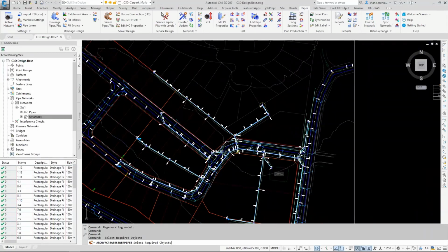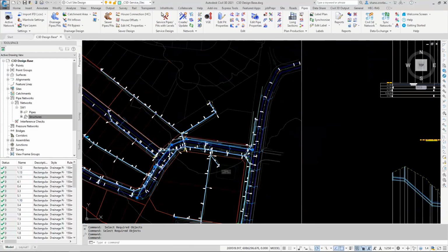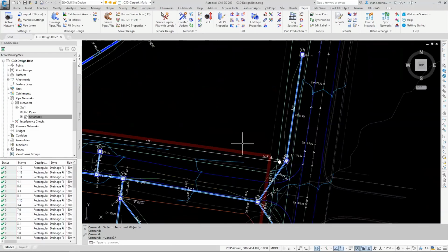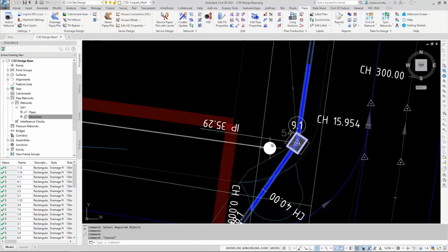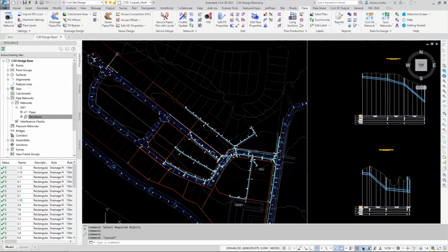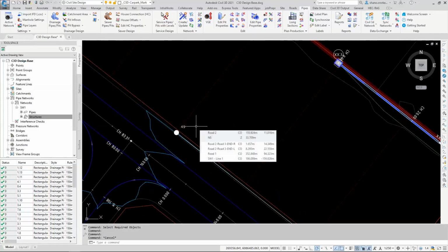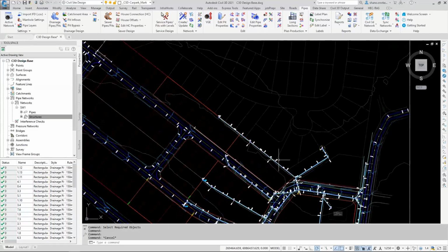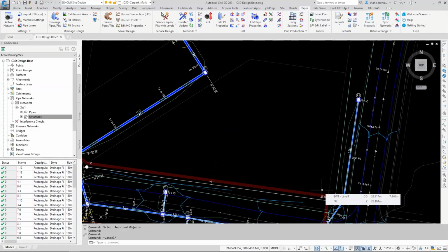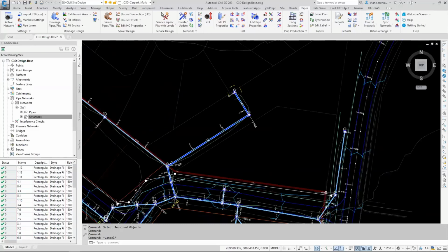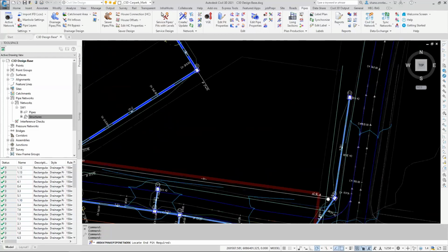And I've now created a series of pipes and manholes. And my next step is then to go and turn that into a network, right? So I think I want my outlet over here, if I remember low points and high points correctly. Let's just see what Civil 3D says before I pick incorrectly. 33.7 elevation over here, 32 point 28, definitely this is my low point. So I'm going to run a gravity sewer. I'm going to turn this into a network.